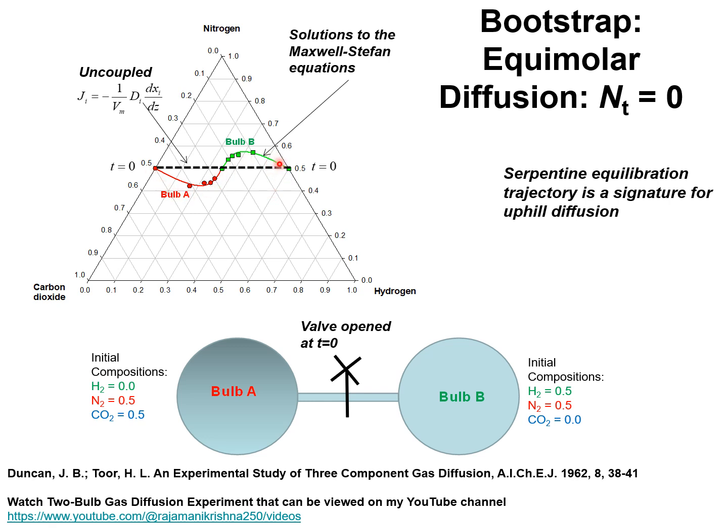Indeed, the solutions of the Maxwell Stefan equations using the Krishna Standart matrix procedure is indicated by the continuous green and red lines. These solutions invoke the equimolar diffusion constraint imposed by the momentum balance.